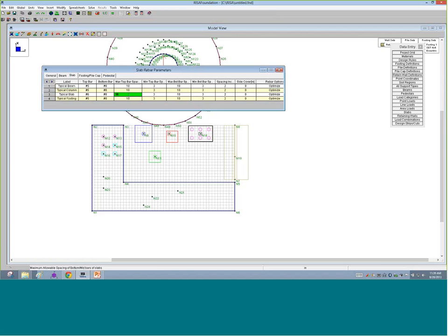Just as I mentioned earlier, if you decide you're doing more of an analysis of an as-built or a situation you already know, you can set these values to be equal, and then you'll be checking what you currently have. So we'll let the program design this for us, though. So we have an 18-inch and a 3-inch. It's going to space the bars all the way from 18 down to 3 as needed.